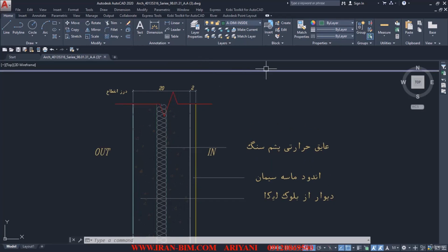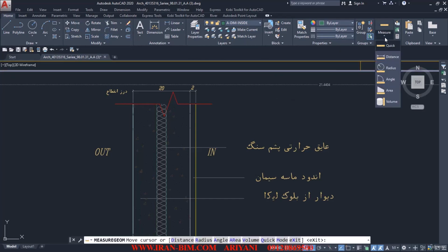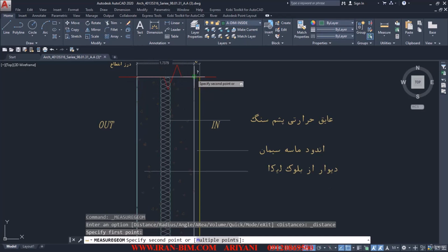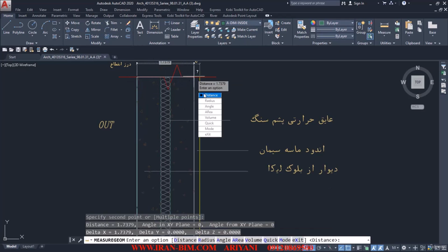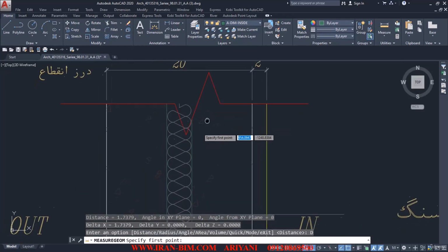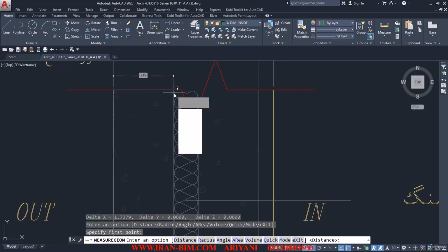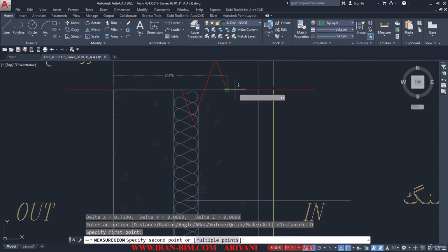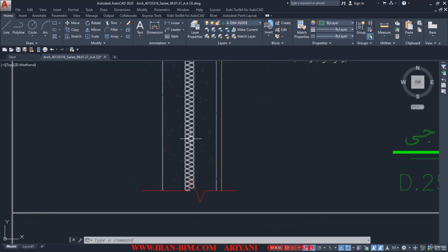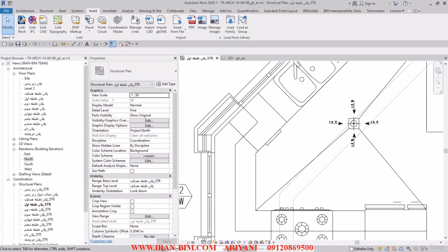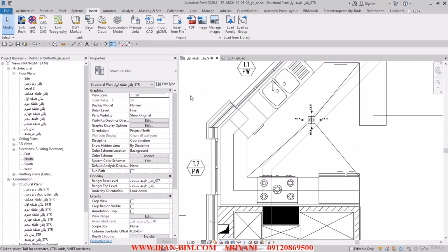So I get the dimensions option and I measure it from this point to this point here. So let's just pull this from here to here. We have a 7.5 here, another one. It seems we have two 7.5s on the side and then a 5.5, I think, in the middle. And so we pop back to the Revit file, and then I select the wall option here.